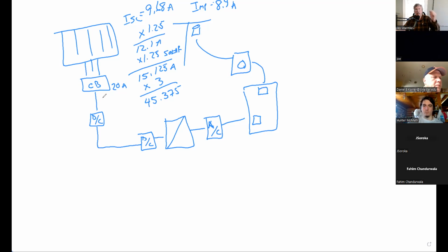Well, if it turns out that both lugs are rated at 90 degrees Celsius, then you could go with column 3 with the higher rated wire, but you might change out that DC disconnect in the future, and you don't know what the rating of that lug will be. So if you go with the lowest temperature rating of the wire, you're always going to be safe, regardless of what piece of equipment you connect on either end of it. All right. Have I confused anybody with this?